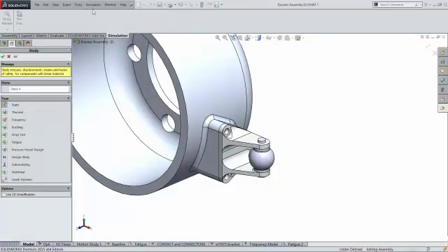So when I start simulation, when I have the real package, of course, I have a lot more options in terms of modules or tests that I can run. And we'll do a couple of them here in about 10 minutes. But obviously static, right? Linear static are bread and butter. What's my factor of safety? Is it going to fail? What does my deformation look like? So we'll begin a new study.